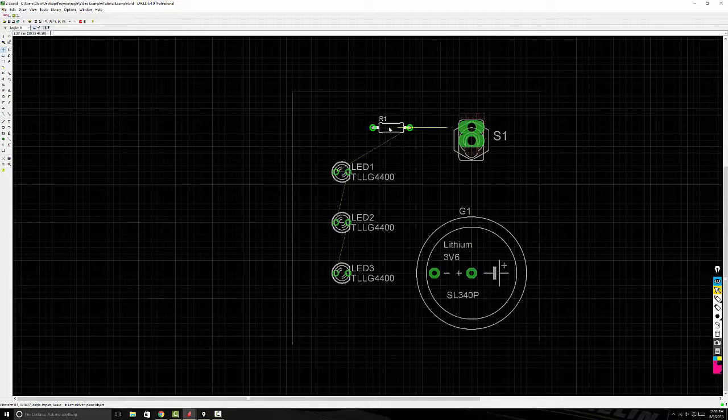So what you want to do is organize your components in a logical manner that makes your board look clean, neat, and organized, and minimizes how many of these air lines are crossing one another. Because, like I said, these are going to turn into your PCB traces. So the more crossing that you have on these traces, the more complex your board is going to be. You're going to have to use more vias to switch to different layers, etc. So make it as clean as possible.